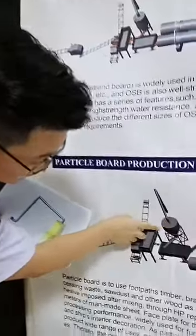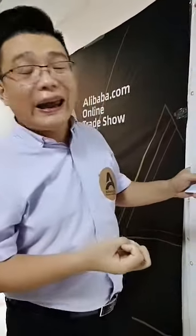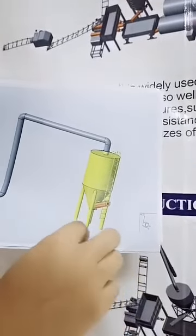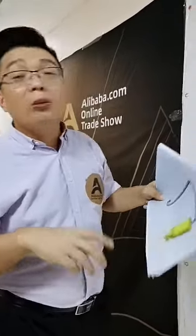When the air blows, wood is always thin and light, so it will be blown into this silo. But some sand, dust, or stone cannot be blown by the air, so it drops from here through a tube to the ground. So we call it the cyclone separator, to separate wood from the dust and also the sand, stone, or metal.